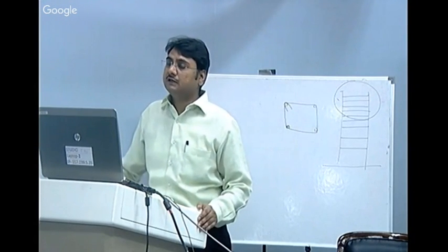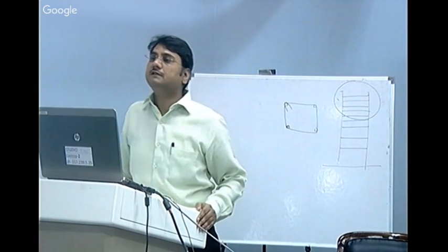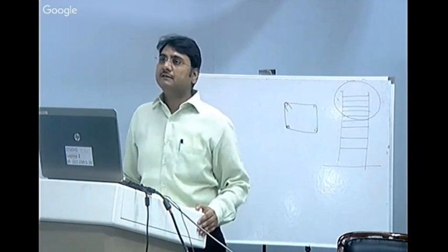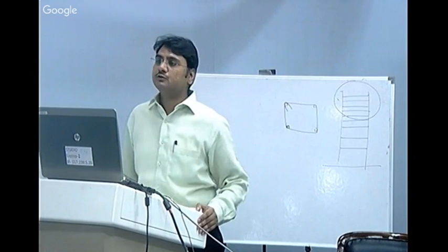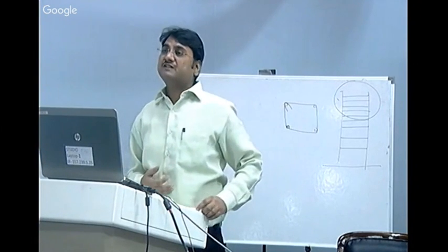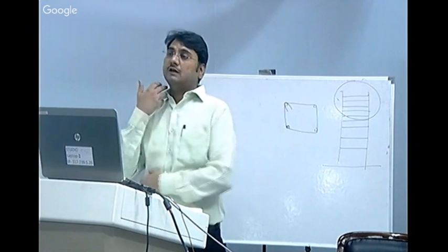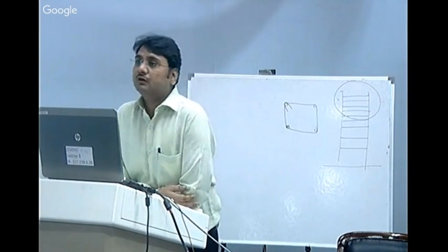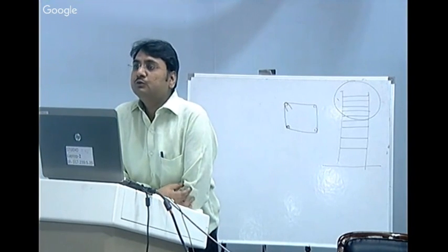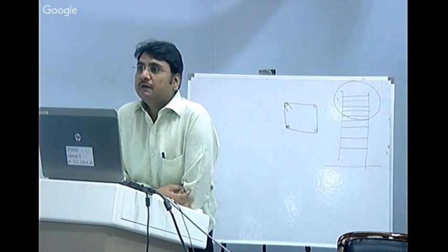After attaining a deflection of 10 centimeters, the structure came back to its original position. So we are thinking that in framed structure also, in case of infills, it will create much less pressure on the column. If it creates less pressure on the column, it will transfer less shear force to the column. So we need to design the column accordingly.